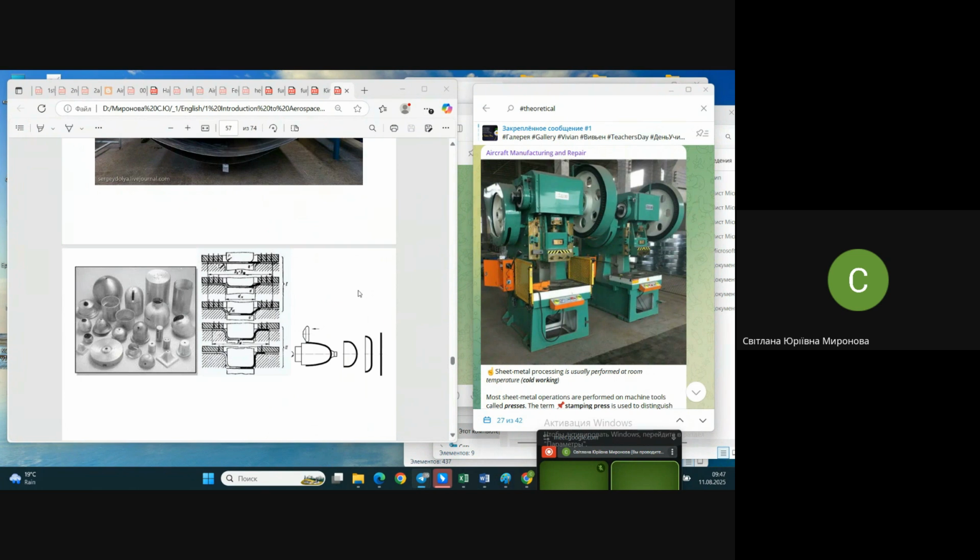When it comes to using special dies, special or half universal, like the dies with rotatable elements, first you need to design the die, which takes some months. You need to produce the die, test it, and only after that may you start the work. After this, of course, your work looks like shooting, because press working is quick. But before this, you spend money, time, and labor force for some months. You invest all this, and only after that will you have some payback.